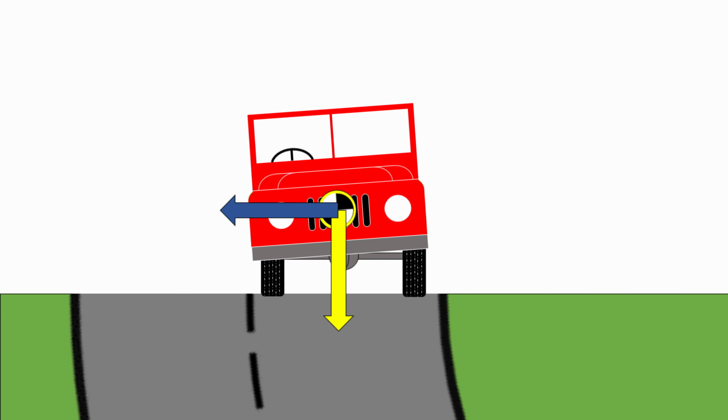It is of course possible for a vehicle to become unstable simply from trying to turn too tightly. If you apply a very hard steering force and try and describe a very tight circle, particularly if you're travelling at high speed, the vehicle can overturn even on a flat road. Generally, certainly vehicles on tarmac tend to run out of traction before they run out of stability, so they'll usually skid rather than roll over. But not all the time, and it is possible to roll vehicles over simply because of the manoeuvre that they try to perform.